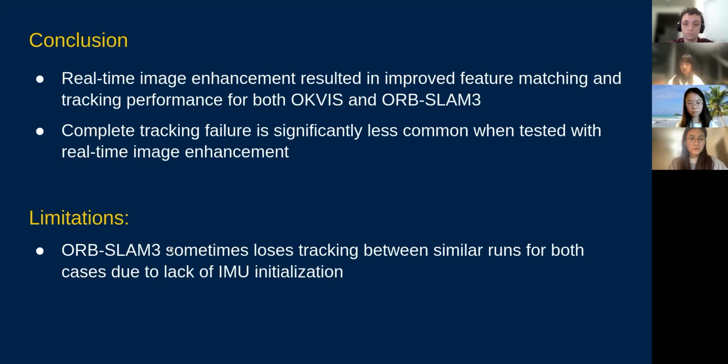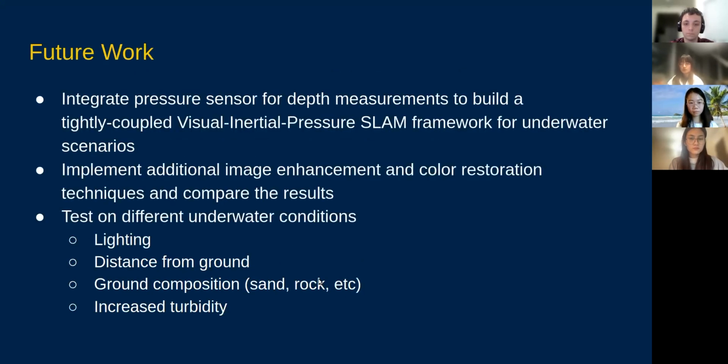One limitation that we faced was that ORB-SLAM3 sometimes loses tracking between similar runs for both cases, due to the lack of IMU initialization. This could be attributed to the lack of excitation of the ROV, which makes the initialization process a lot harder. Coming to future work, we wish to integrate a pressure sensor with depth measurements to build a